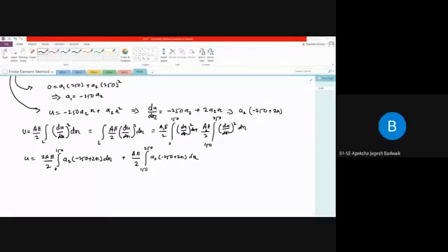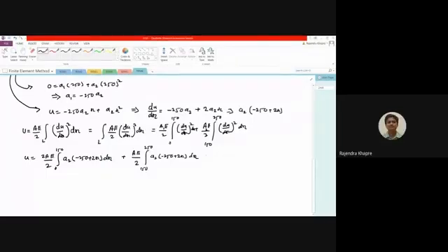Yes, sir. Okay, so this is how you have to go about solving the problem using varying cross section area. If you have different E, you can use different E also in this particular way. Now I am not completing this problem, you can complete it on your own. I just wanted to tell you how to deal with the multiple values of areas when you are solving with the Rayleigh Ritz method.